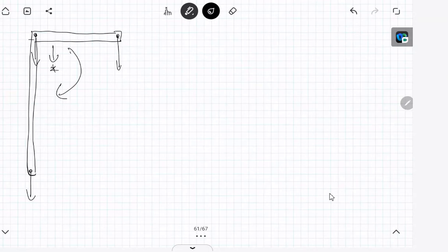Okay, so normally at this point, usually point 3 is the most critical. If the situation is like this, normally point 3 is the most critical. Look, it's blank. The H that you should get is the weld size. You get 12.292.